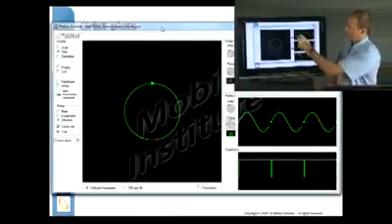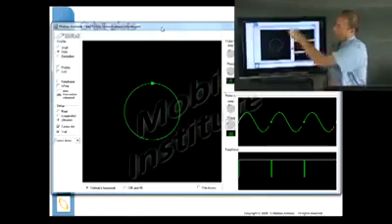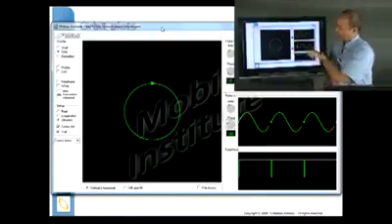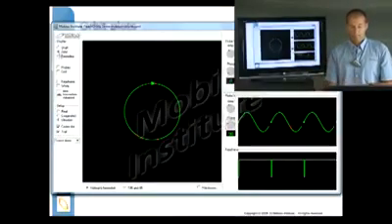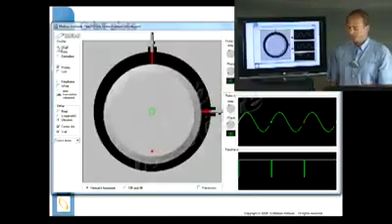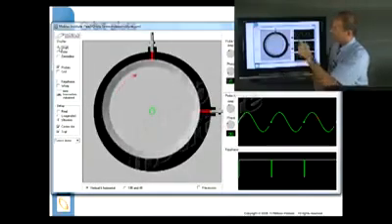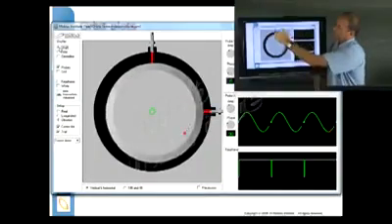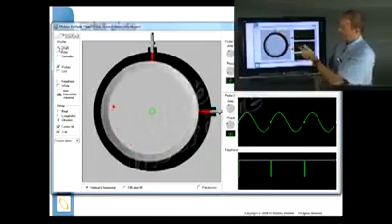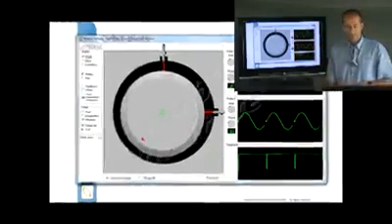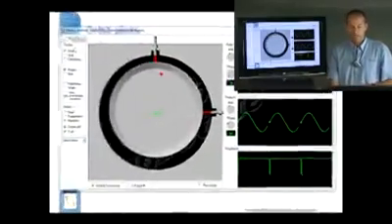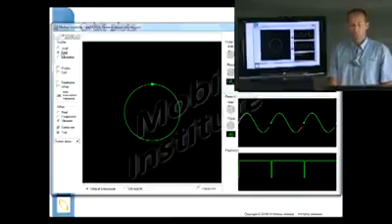So there's the voltage from my Y probe, which was up on top, the voltage from my X probe, and I've also got my key phaser, sort of once per revolution signal, going there. So again, if I show you the shaft, there it is spinning, and this is rising and falling according to the gap there, and this one's rising and falling according to the gap there. When I plot those against each other, I end up with an orbit plot.